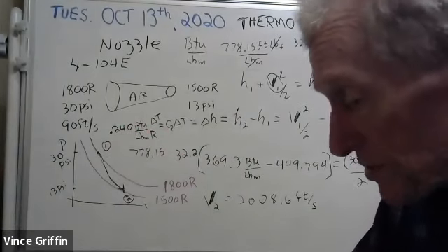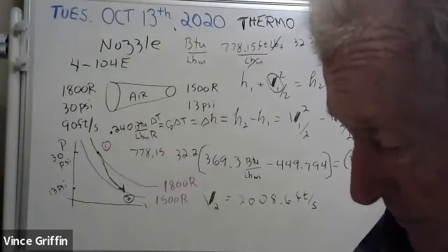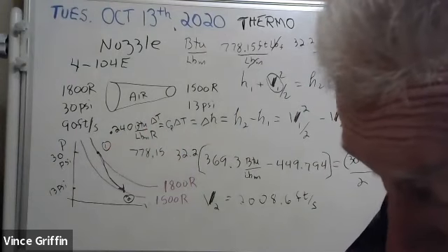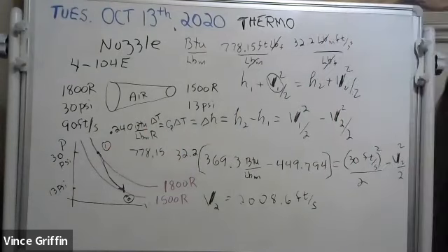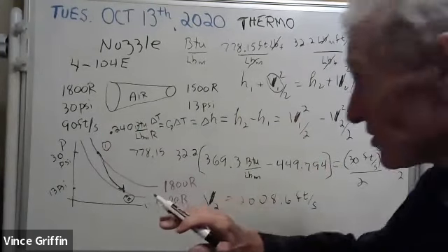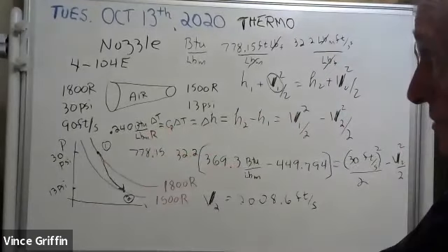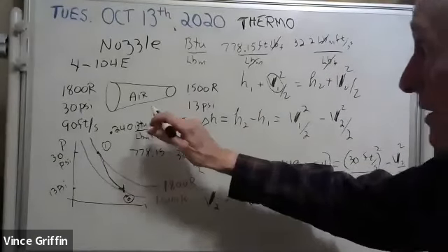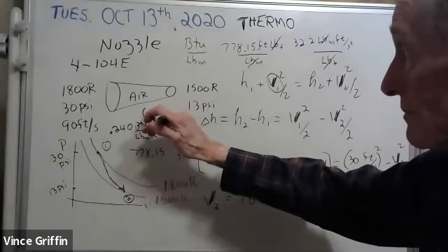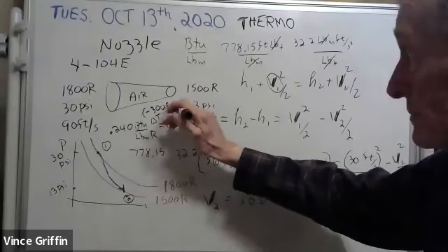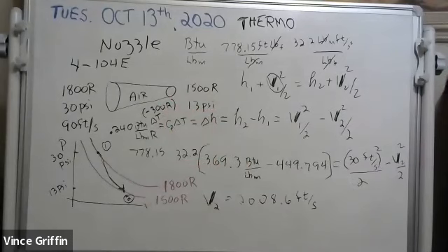You know what I was thinking? I was thinking 1004 kilojoules per kilogram Kelvin. And we're not in metric, we're in English, senor. But now we know what the change in temperature is. It's minus 300 Rankine, isn't it? Okay, now we're going to do that this way this time.